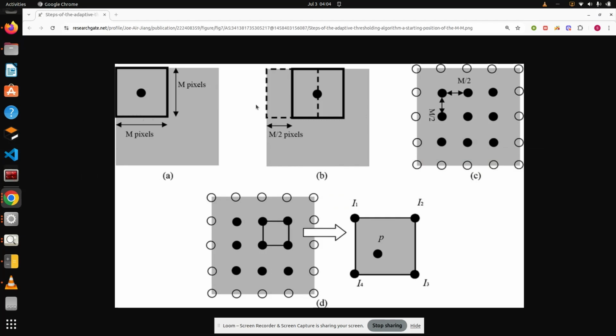In this window, an average is calculated. Then the pixels of the window are analyzed, and if the value is above a certain threshold, we assign the same value to the entire window. This is done so that it will be easier for us to identify which squares are shaded with which color, and then we can identify the set bits, and accordingly identify our ArUco tag ID and the associated details with it.